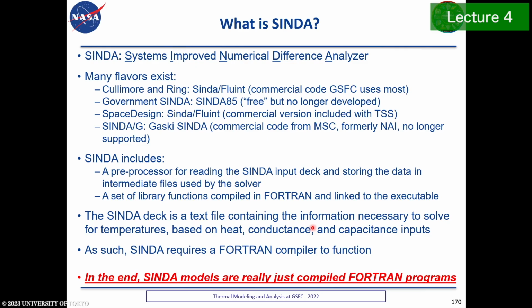CINDA includes a preprocessor, which reads your CINDA file and stores the data that it needs in a binary format so that it can read it. And then there's a set of library functions that CINDA provides, which together with your user logic, it compiles, accesses the data, and basically runs your simulation as a Fortran program. So the CINDA deck is a text file.